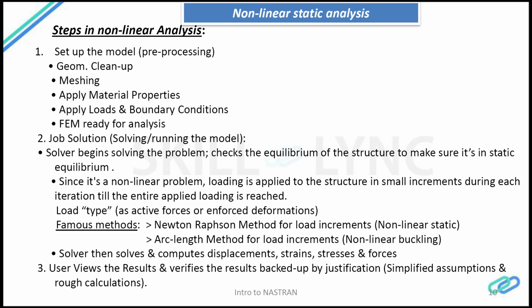In the second step, since it is a nonlinear solution, the loading applied to the model will be in consecutive steps, in increments. So the solver will start to solve the problem once you submit the job, and first the solver will check the equilibrium of the structure, make sure that it's a static problem, not a dynamic problem or a rigid body motion problem.